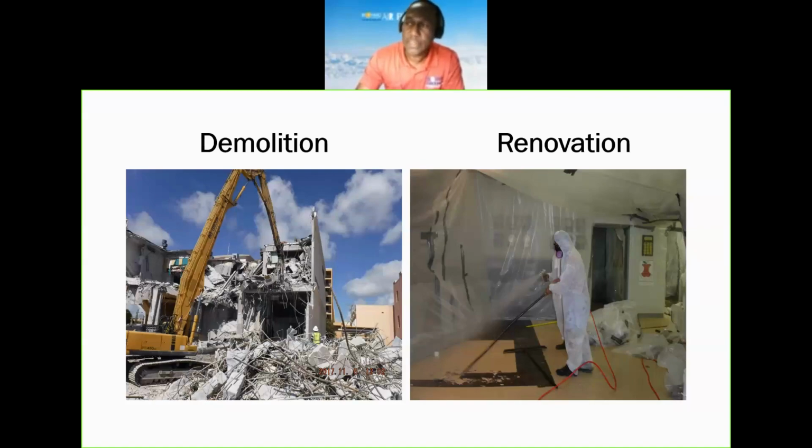On the right, what's considered a renovation by NESHAP would be an abatement with removal of asbestos. Any alteration or any removal of any work that's going on that requires roofing projects, flooring, any drywall that's been knocked down, or popcorn ceiling removal. All these projects fall under renovation under NESHAP. Next.